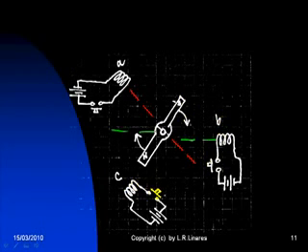At that point, I push the button of coil C, and then I repeat that again with A, B, and C. And by keeping on pushing and releasing the three buttons of coils A, B, and C, I have created a rotating machine, a motor. I have created a situation in which a magnetic field is jumping from coil A to coil B to coil C and back to coil A. We have a rotating magnetic field, and the bar is chasing that rotating magnetic field in synchronism, rotating with that magnetic field.